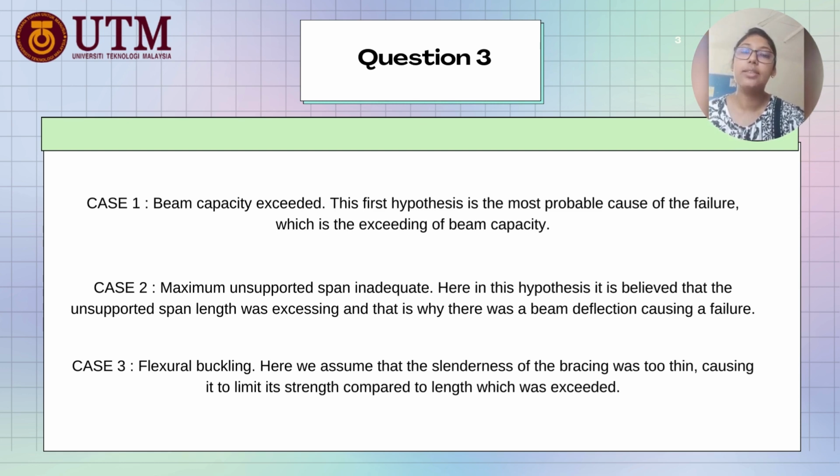So the rack is supposed to be empty and stationary, but a lift truck falls from a specific height, which will cause the collapse of the structure. In question number 4, we have shown an example of that as well: from a height of 1.4 meter, if a lift truck is dropped, it will collapse.